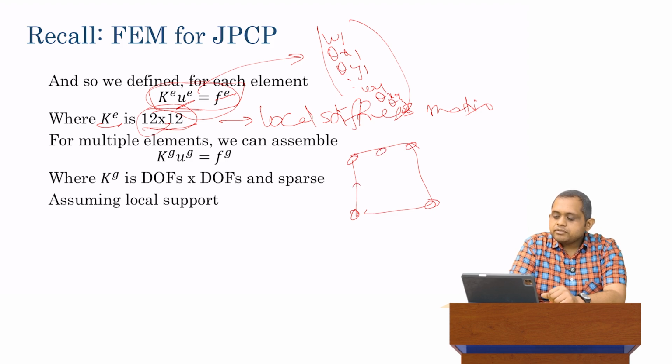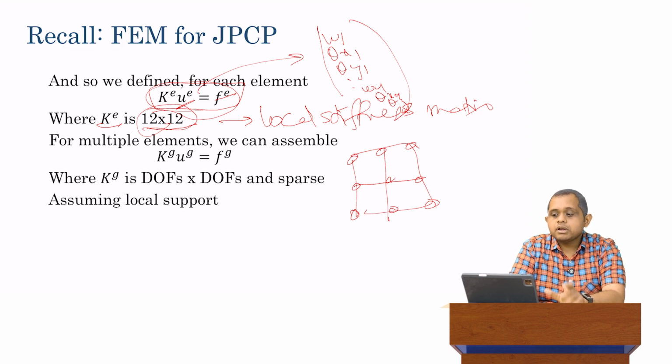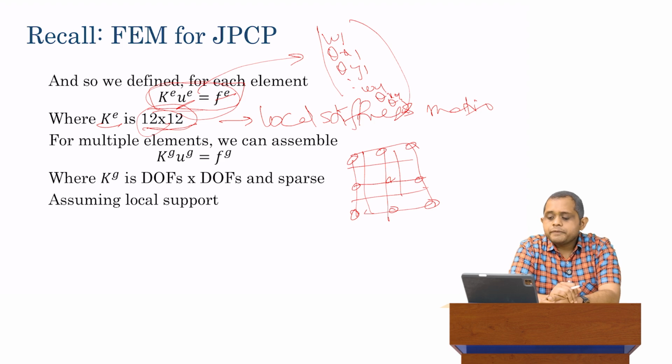We may have to divide it further. So, for example, along each direction, I'll divide into more nodes, and then instead of a 1 element approximation to the slab, I have a 4 element approximation of the slab. Similarly, I can have a 9 element, 16 element approximation, and so on. So we usually need to have many more elements in order to approximate the behavior of the slab.